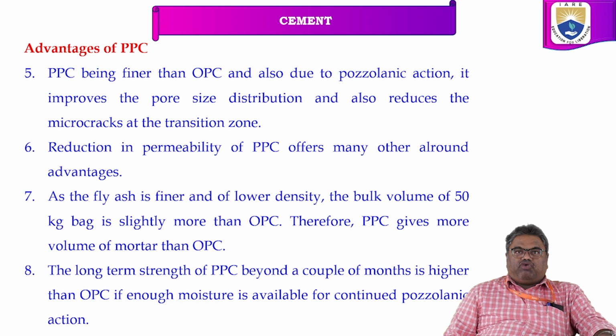PPC being finer than OPC, and also due to pozzolanic action, it improves the pore size distribution. It also reduces the micro cracks at the transition zones. So it is going to reduce the cracks in the transition zone.